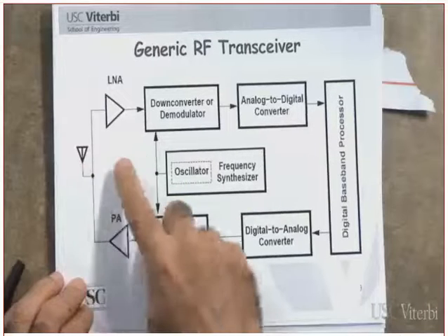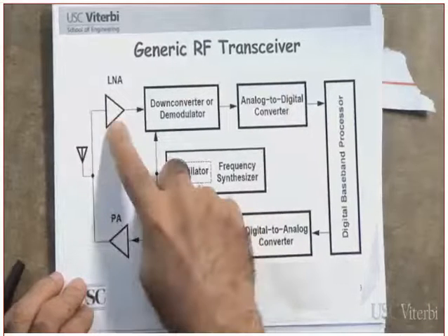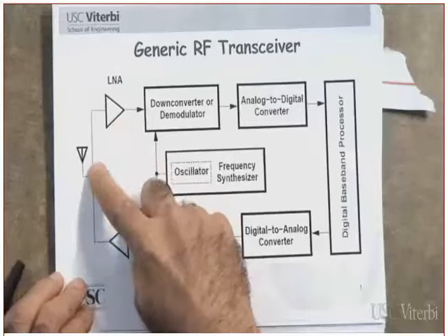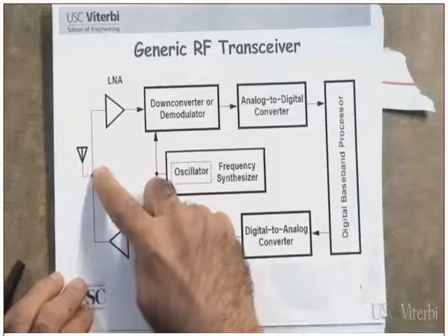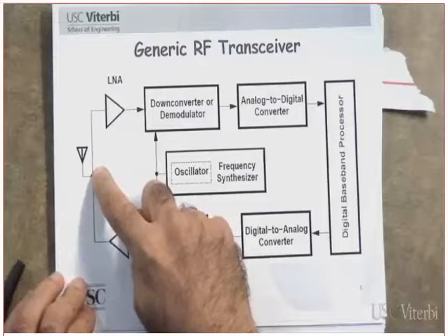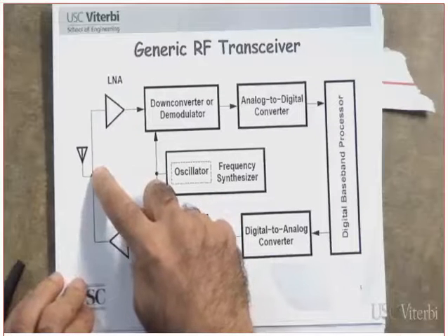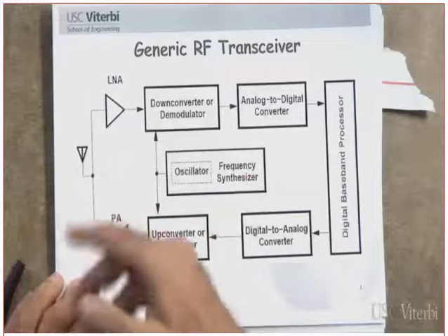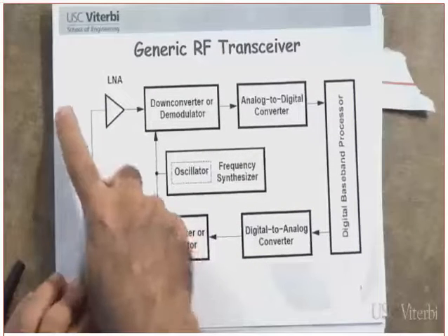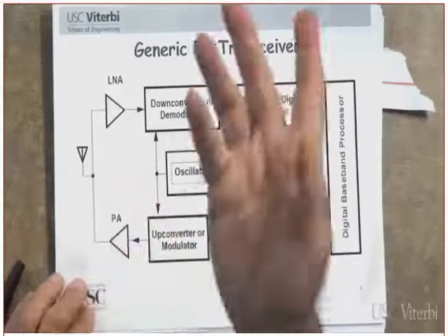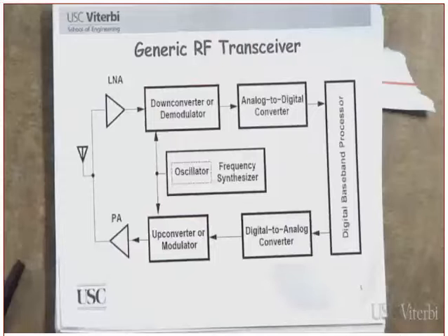This is the antenna. Now, on the other side, this is the receiver. Again, the low noise amplifier. Why did we say that last time? We said that the received signal is going to be, first of all, very weak. And in addition to that, there will be a lot of noise associated with it. Remember, by the way, the noise that is coming from outside is thermal noise. And the thermal noise has a large bandwidth. We need to get rid of as much noise bandwidth as possible.